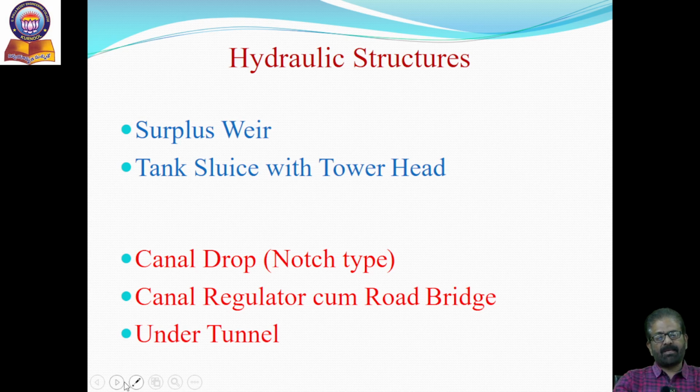Similarly, the second one is the canal regulator cum road bridge. This is some sort of regulation work. Regulation means having shutters or gates to regulate the flow in the canal. Often these regulators are combined with road bridges.